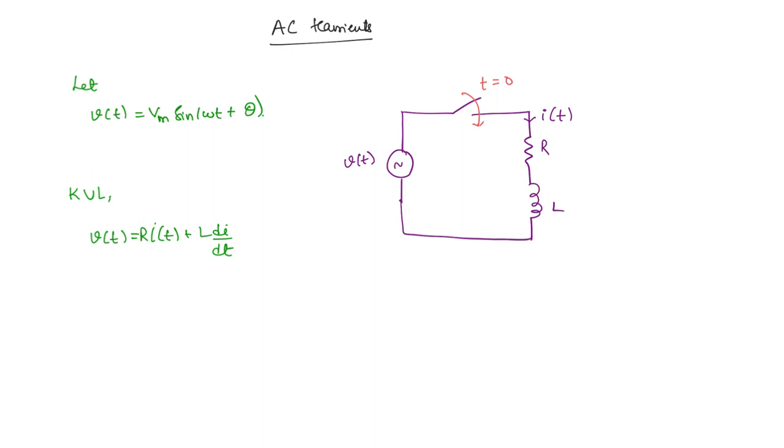Okay. So the differential equation method, you will get a complementary function and a particular integral. This is from mathematics, but don't worry even if you don't remember. This complementary function you will get as the response because of the initial conditions. So that means you will equate input to 0 and you will solve the differential equation to get the complementary function. And the particular integral will be due to the input. Okay, and this you can get by steady state analysis.